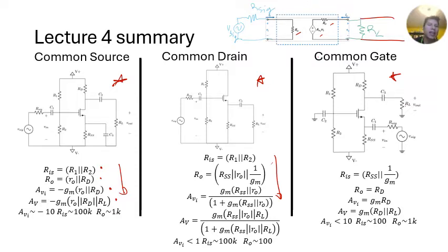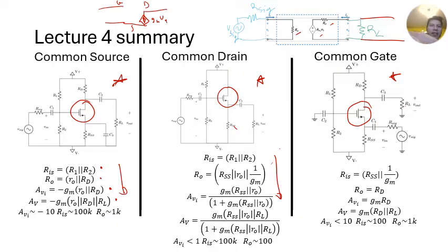And in particular, we said that first we were going to replace our transistor with our small signal model, which is basically, if this is the source, this is the drain, and this is the gate, then you have a voltage controlled current source, gm VGS, with plus minus VGS, and then there is a little RO associated with the channel length modulation. And then we said we were going to replace our transistors with this pi model, and then we were going to derive our